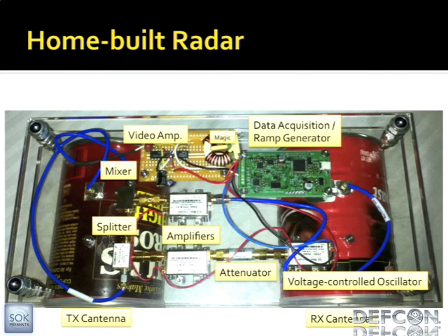So the reason that's there is because when I was trying to make this thing USB powered, I just wired it onto the power for this other stuff. Everything on here runs off of 5 volts. So I plugged the USB in, and the computer doesn't like that. It just turns off the port. The problem was the inrush current was too high, and I needed something to slow that down. So I was like, okay, I'll put an inductor in there. And the only one I could find was this big choke transformer thing. So I just shoved that in there, and that worked. So that's all that's for.